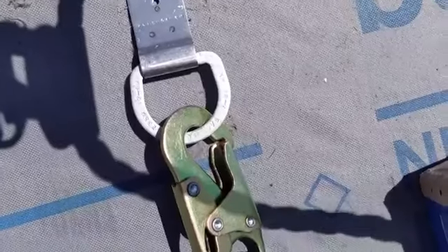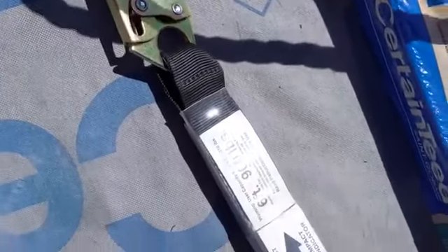If our energy absorber is above that leading edge towards our anchor point, where that point of friction has happened, our energy is not going to transfer up to that anchor point or to where that shock pack potentially could be. It's not going to be controlled and decelerated down to an acceptable level, either the 1,800 pounds or 900 pound average by ANSI, and the worker could be subjected to higher arresting forces or fall forces there.